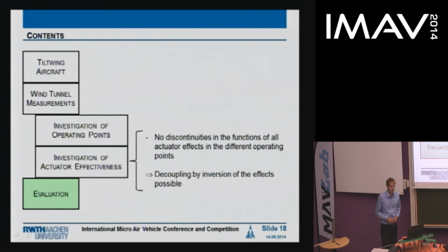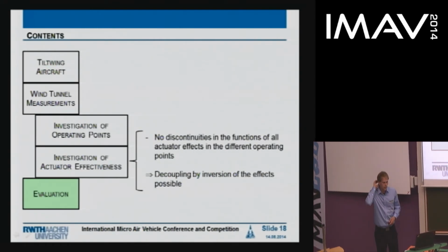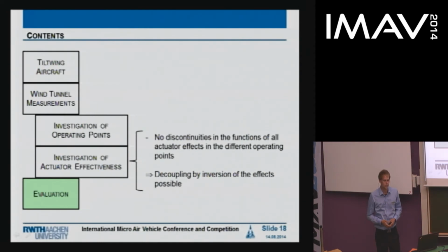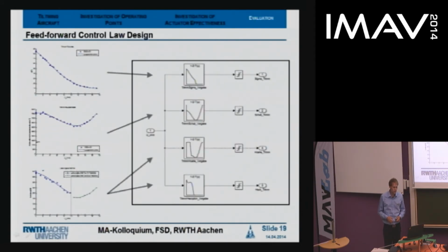And for evaluation purposes, we performed a second wind tunnel measurement with an identical setup, only that the MAV was now connected to the weighing scale by a ball joint. This means it's allowing rotational movements around the center of gravity, but the forces are still recorded by the weighing scale. During this measurement, the actuators of the longitudinal motion are steered by the FLUCO.